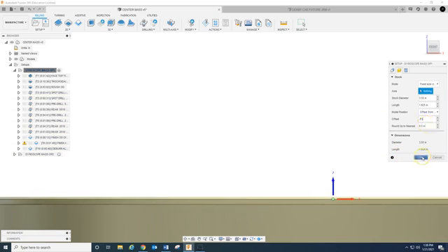And the more you machine, the more that's going to make sense to you. You never really want to set offsets off of stock whenever possible. You want to set them off of your part.